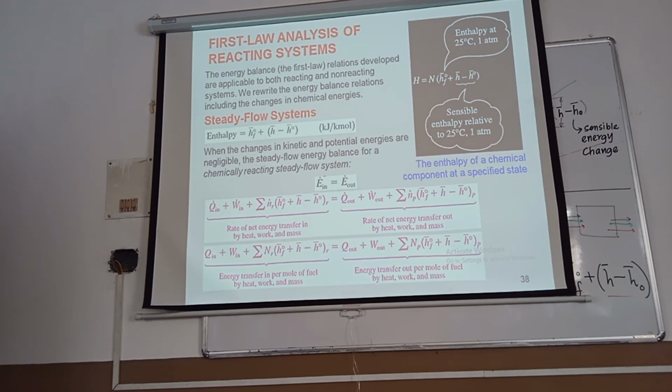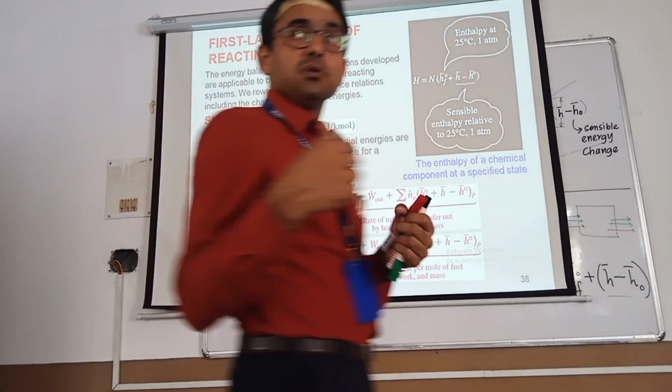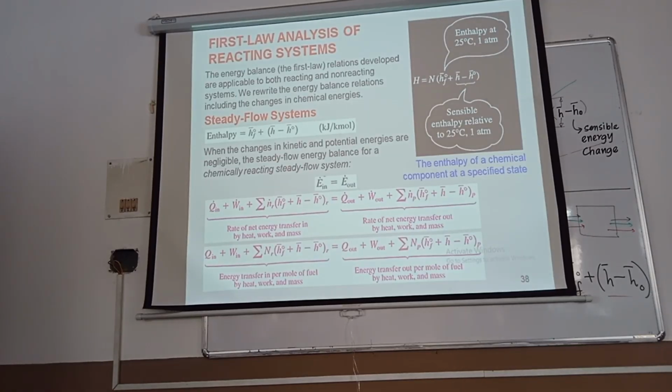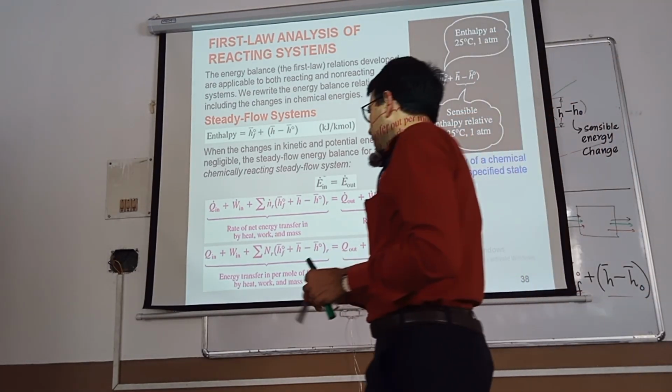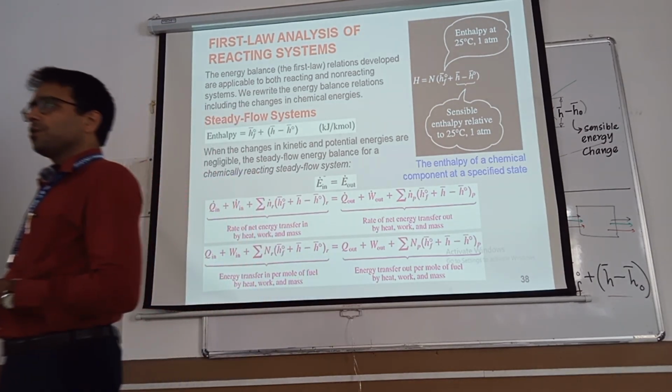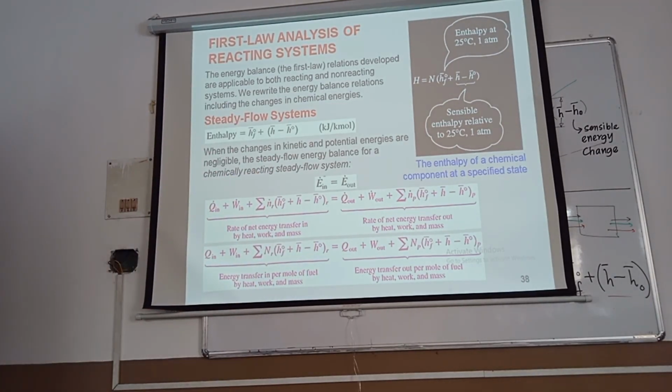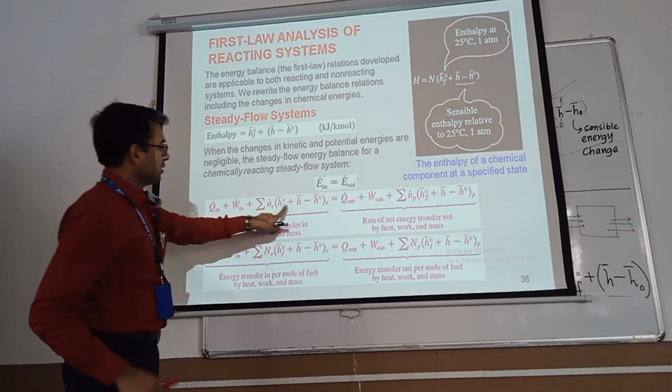Right? We will discuss compressible flow just after this. During compressible flow, definitely kinetic energy cannot be neglected, because compressible flow means there is flow generated due to the change in enthalpy. So they are comparable. That means from enthalpy you can generate flow, right? So in that case you cannot neglect it. Otherwise, in most situations you can neglect the kinetic energy and potential energy. Okay. So this is the internal part.